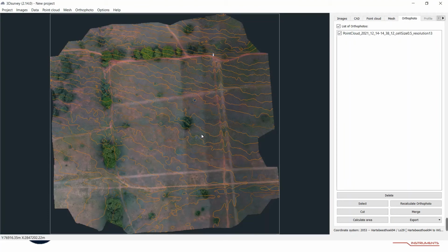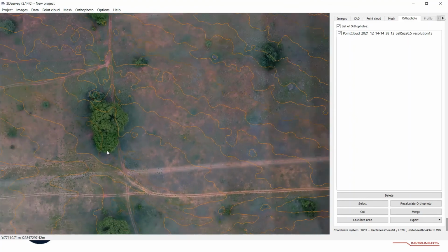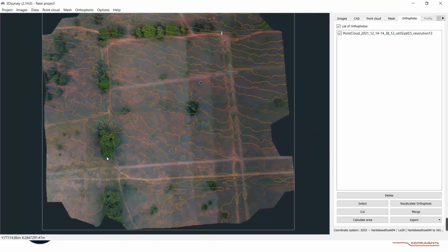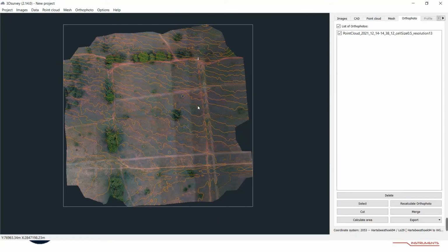Alright, and then as you can see, this is my contours draped over my orthophoto, and my orthophoto has in fact got my original trees back. So it still shows a normal contour flowing through the tree, even though you can actually see the tree. So it doesn't make any spirals like it would have if you had the trees visible, and that's why we do a ground classification.